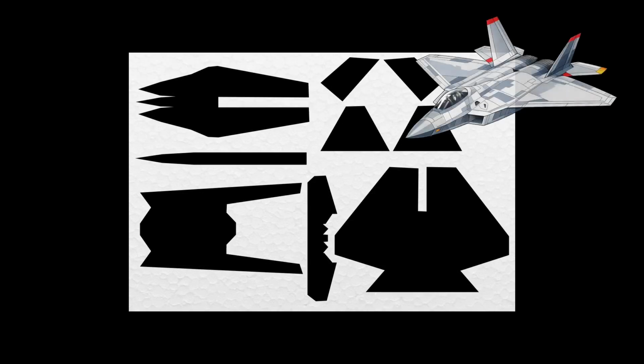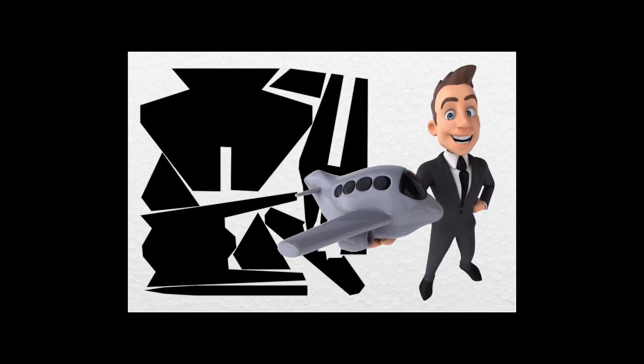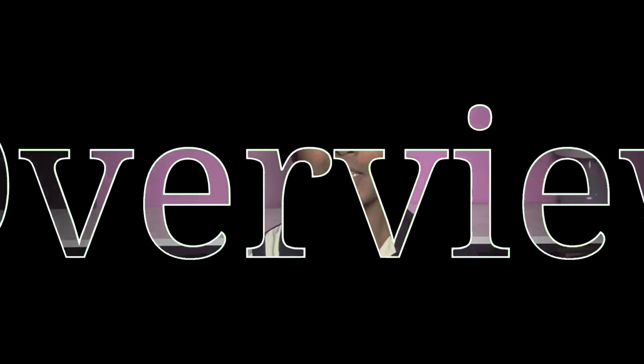Most of us waste a lot of foam board while building an airplane. Let me show you how you can use Blender and Python to minimize wastage of foam board and build model airplanes like a pro. I will split the tutorial in two parts. First, I will show you how to use Blender to trace individual parts of an airplane. Later, I will use a Python script and a 2D packing solver to find a tight packing of parts on